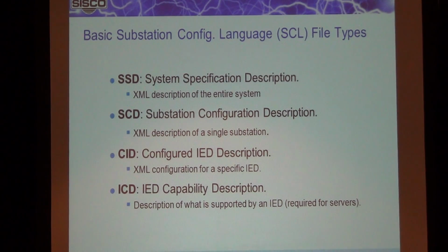And then there's an IED capability description, an ICD file. This is produced by the developer that tells you what the device is capable of. The only requirement in 61850 is that any device that passes conformance test has to have an ICD file for it.